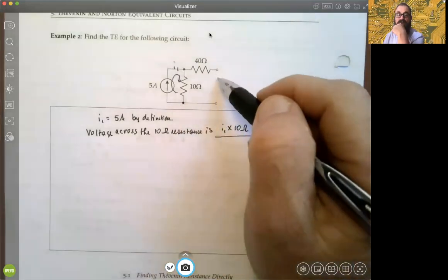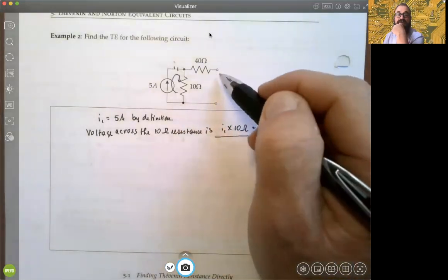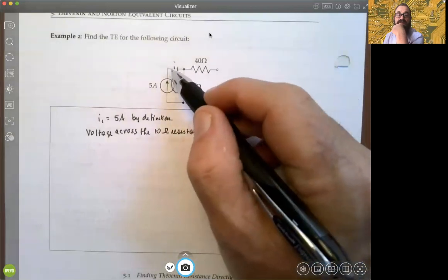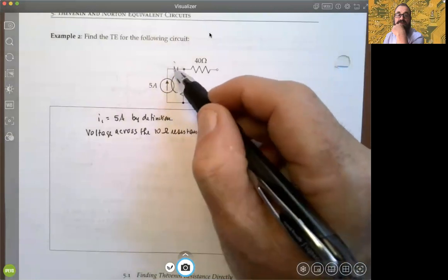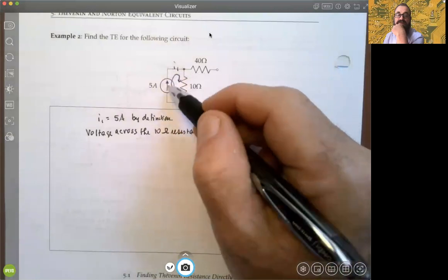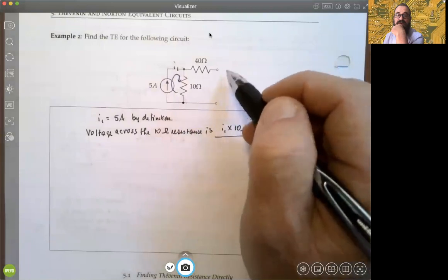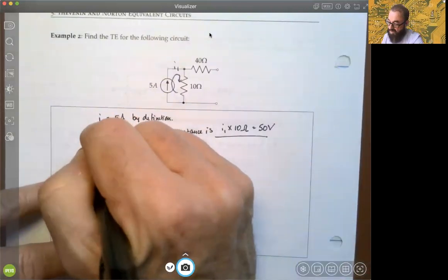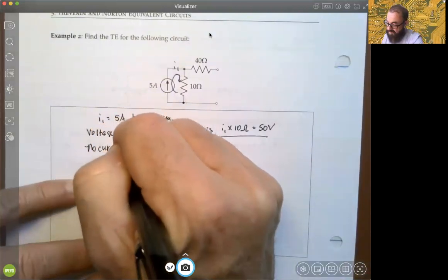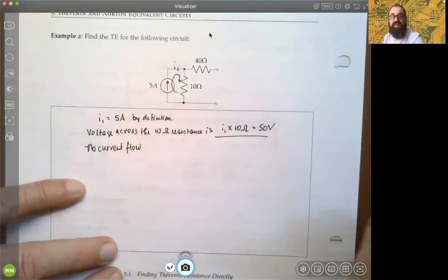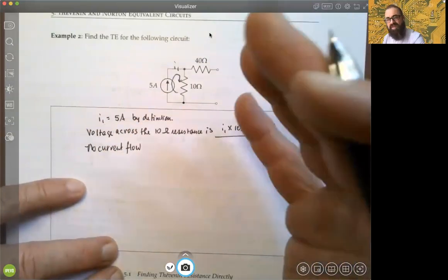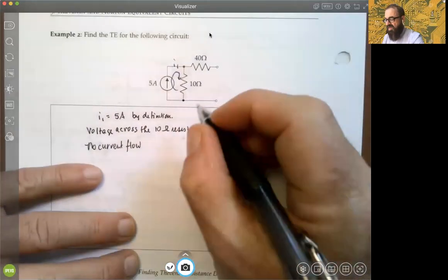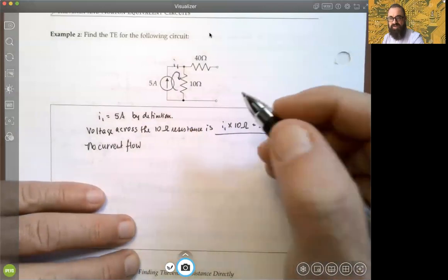Again, there's no current here, okay? So if there's no current here, then this current will only come through these terminals here and go around and around and around with that voltage source, because there will be no current coming out here, okay? All right, so that's cool. So let's make a note of that, no current. This just helps us understand how to think about these. I'm just writing this to make sure that we clarify. I'm not saying these are obvious observations, but we've got to make sure we understand the meaning and interpreting these open and closed circuit components.